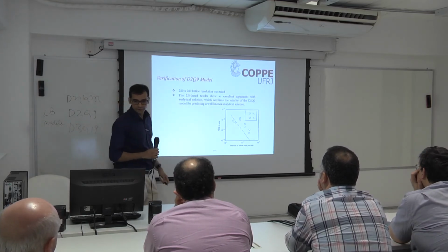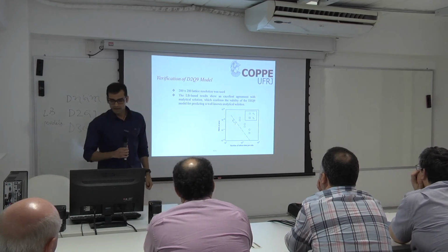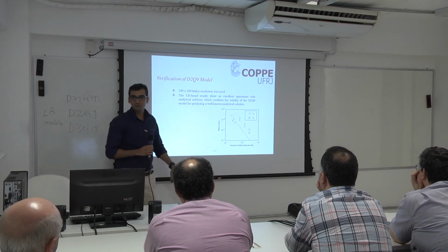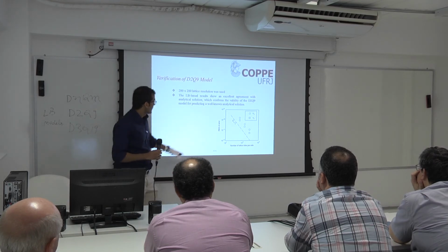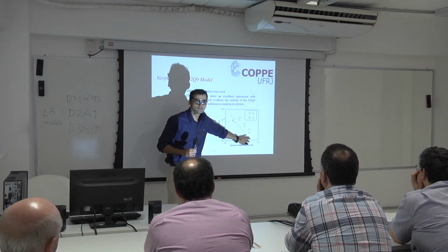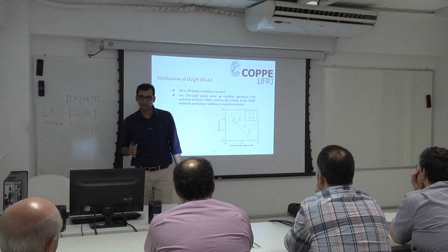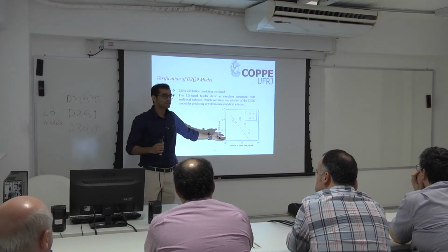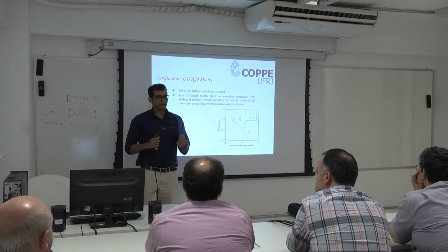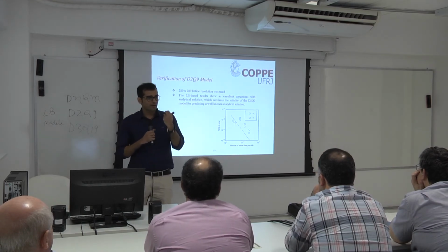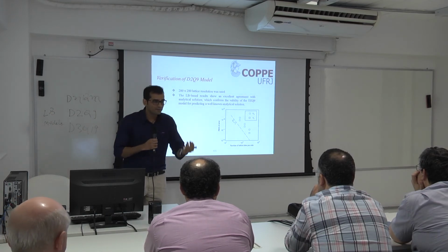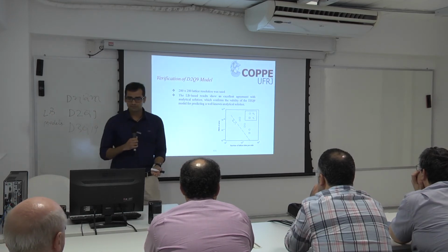Now the verification of D2Q9 models. As you can see, a 280 by 280 lattice resolution was used by Wannier. And see, this is the root mean square error plot. What do you see? It clearly shows that the more lattice points I put into my window, the more efficient my simulations would be.